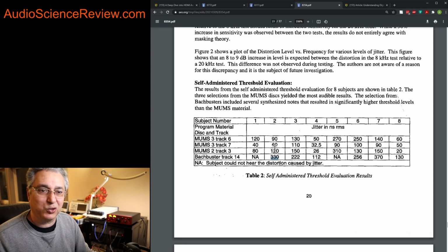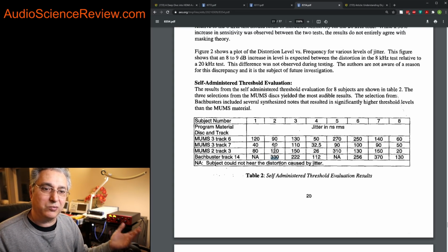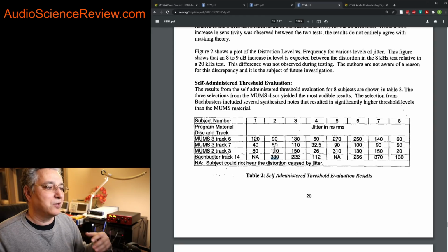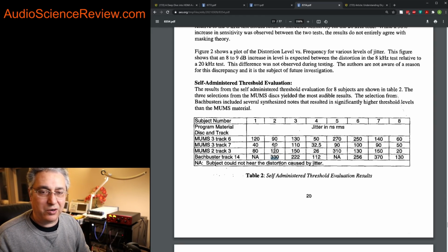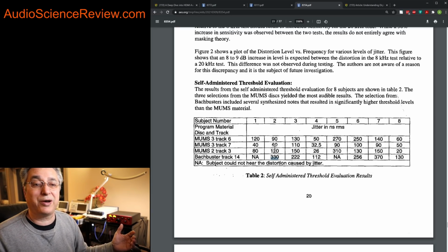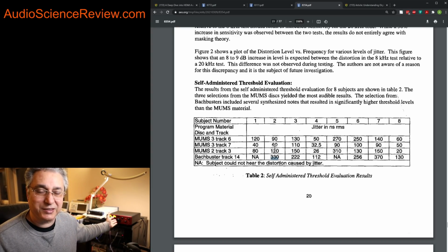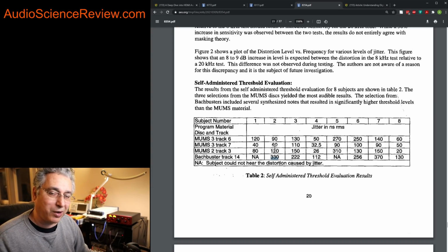Yet 90% of audio tweaks for digital audio, for cables or stuff to put under it, or a fancier DAC, they talk about how transients get better. No, it has nothing to do with timing. It has to do with the spectrum of music that can get corrupted. I've measured 400 DACs. Maybe 1 or 2 of them had objectionable jitter as far as audibility. So it's a solved problem, but as you saw with this device, there are still people not doing the right things.